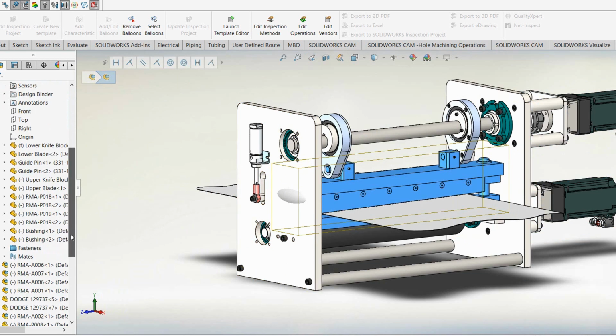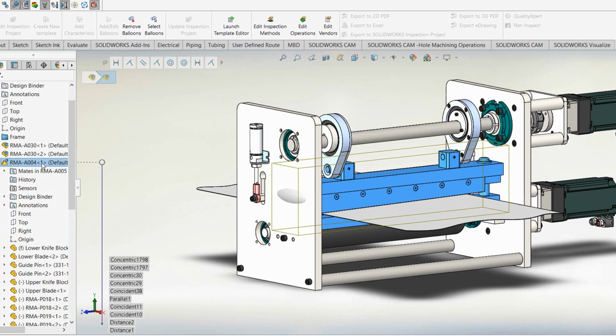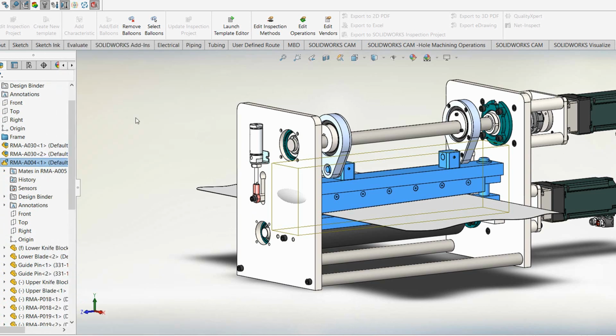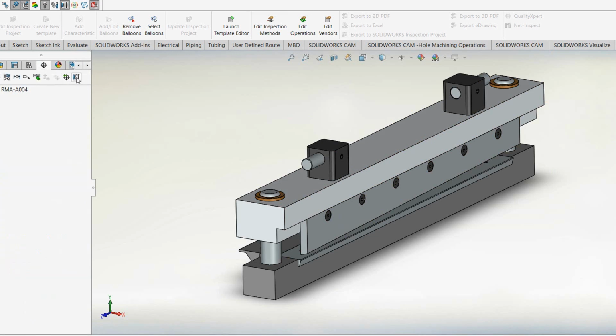So we have something called the TolAnalyst, and those of you who already have a professional license can take a look at that. We have a tolerance study that can be used inside SolidWorks to check our tolerance stack-up analysis. But please be informed that this is a linear stack-up analysis, not a dynamic change analysis.